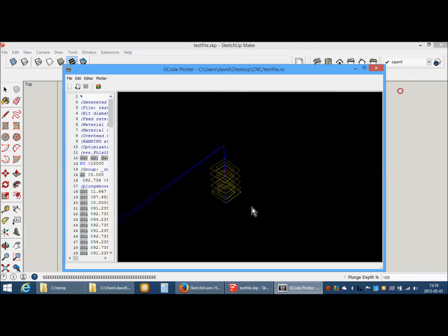Another improvement in the G-code generated by SketchUcam 1.3 is that the helical arcs output for plunge bores are no longer a single full rotation, but are done in quadrants. The reason for this is that some G-code interpreters sometimes miss a complete arc from a helical bore.